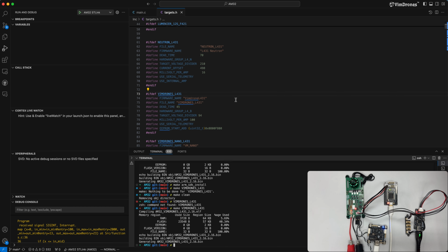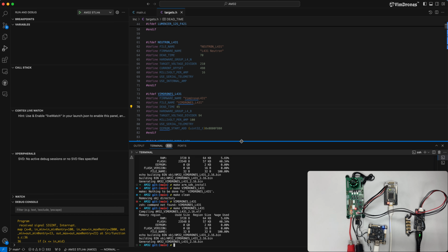Now the bootloader has the SDK environment installed, and the main firmware follows the same process. You need to do the same and install the SDK in your repo. This auto install script also works on macOS, Linux, and Windows. In Windows, you need to install the Make application if you don't have it.